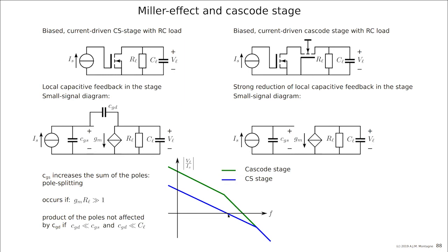And you see indeed that where the green line passes the 0 dB line, it is at a higher frequency than where the blue line passes. So you see that if we did not use this Cascode, we didn't obtain as much bandwidth as possible from this stage. Bandwidth, I should say, contribution to loop gain pole product.